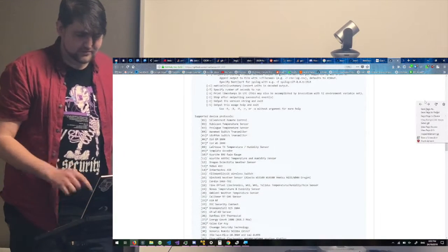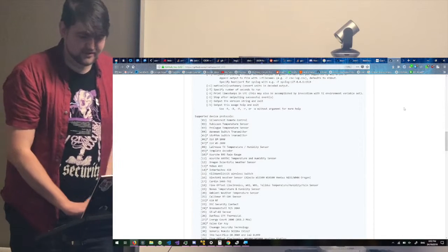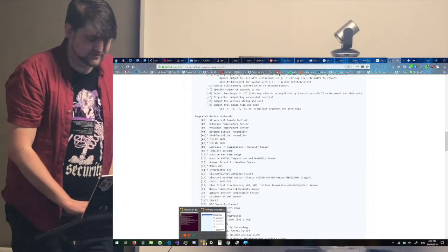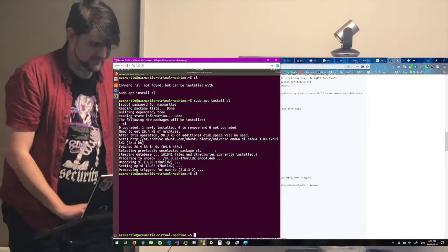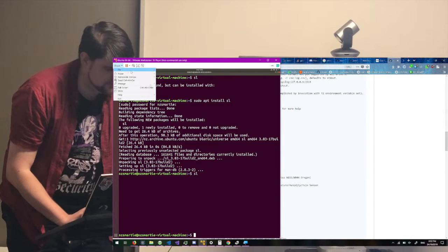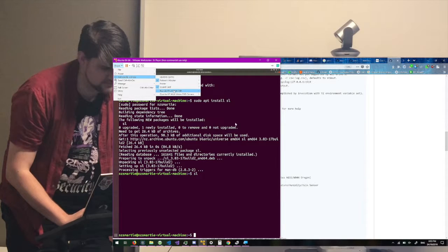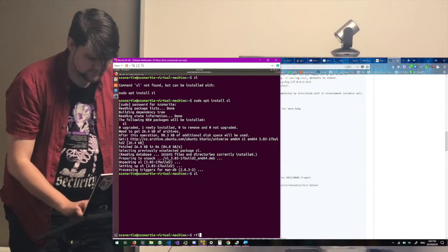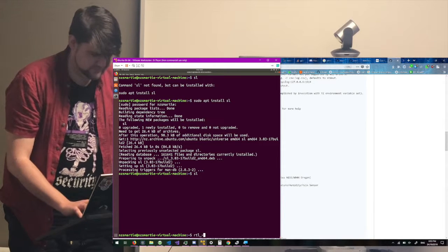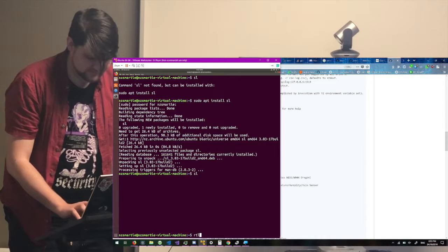Yeah, so if you run the program with no parameters with an SDR plugged in, you'll actually receive everything around you that's transmitting. So I'll actually just reconnect the dongle over here. So we go RTL, so -433. No, maybe it's underscore 433.